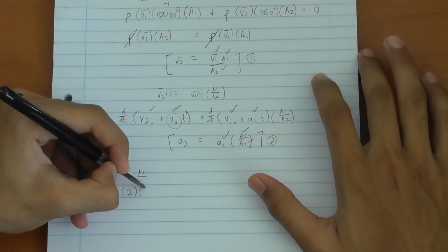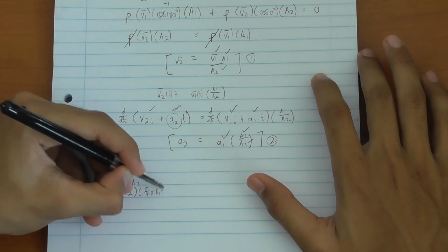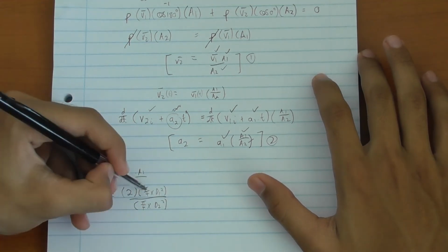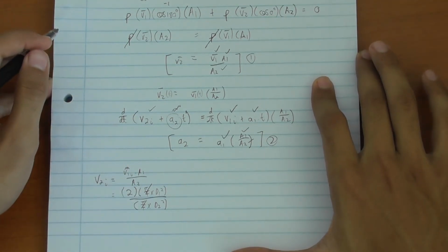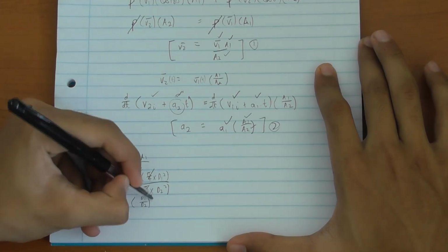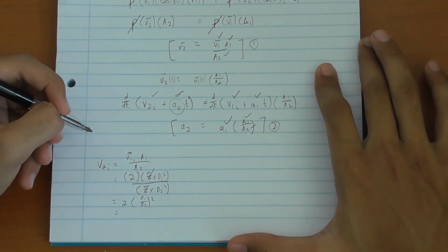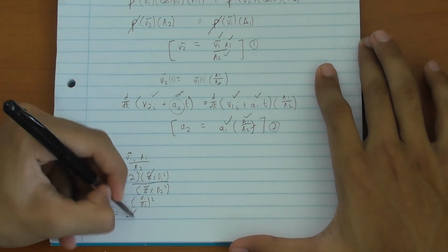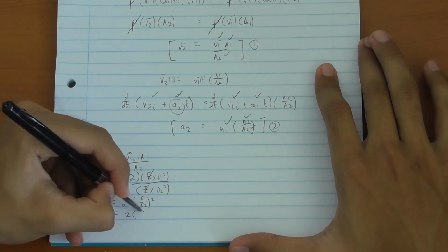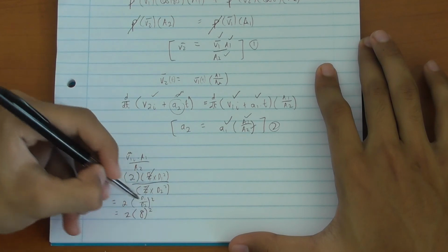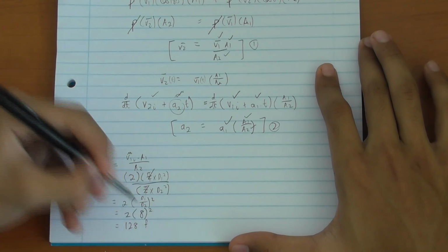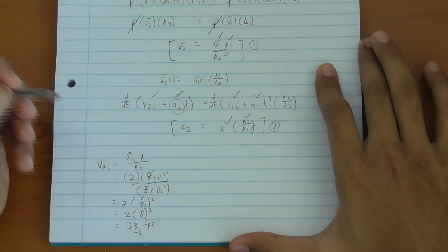So remember, if you're working out area, it's pi over 4 multiplied by diameter 1 squared. But what you'll find is, if I put in the same equation on the bottom, our 2 pi over 4's cancel. All right? So that gives me 2 d1 over d2 squared. And that then becomes 2 multiplied by diameter 1, 4 inches, divided by 0.5 inches, which is 8 squared, which is 64 times 2, which is 128 foot per second.